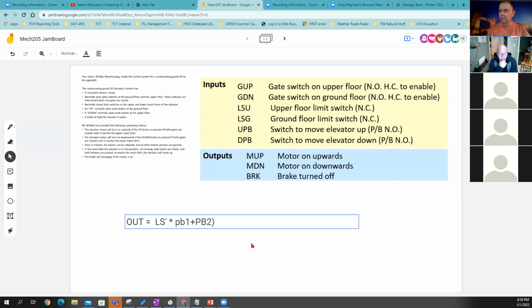And we can put that in brackets, and that bundles them together, right? And if I want to make push button 1 or not push button 2 active low, I can put a prime right there, right? So we can type our equations out this way. Using brackets to create dominance of that particular function, if I want to group them together, you can use brackets. You can use primes every time you want something to be active low, and you can use not primes if you want them to be active high, right?